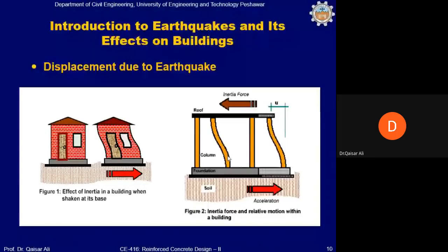However, practically it is almost impossible to proportion such structures, because vertical members like columns and walls would need to be very, very stiff, and they become too uneconomical. For very low-rise structures, let's say 8 or 10 feet high, single-story, it may be possible in some cases, but in most practical situations, it will not be possible.